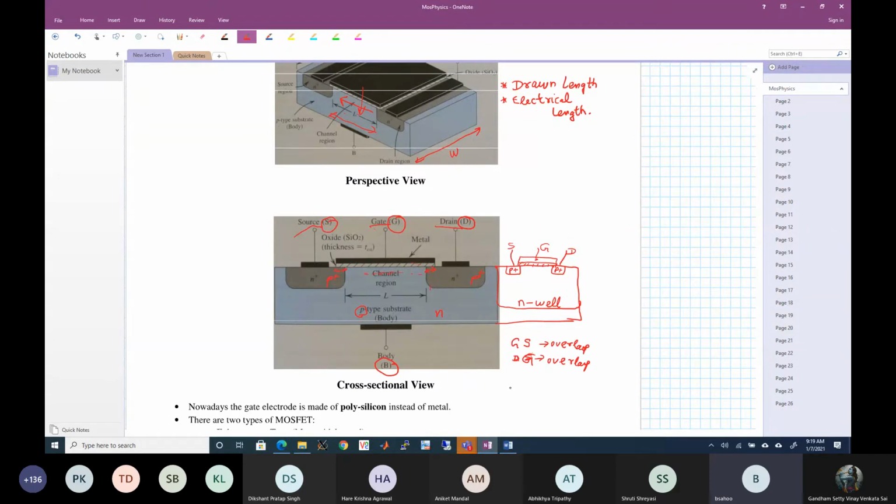So you will see that in electrical engineering, most of the names that you come across have some physical meaning. Otherwise, why is something called a depletion region? What is the meaning of depletion region? Deplete means what? No active carriers present. Depletion means a lack of mobile carriers, yes. I mean, a region that is depleted of carriers, does it have any charge?